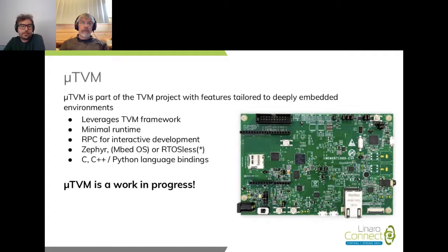It's written in C and C++, and has lots of Python bindings. So the user can use Python APIs to generate final firmware images ready to be flashed and get µTVM running on the targets. And µTVM is a work in progress, so there has been lots of work recently and currently on that front.